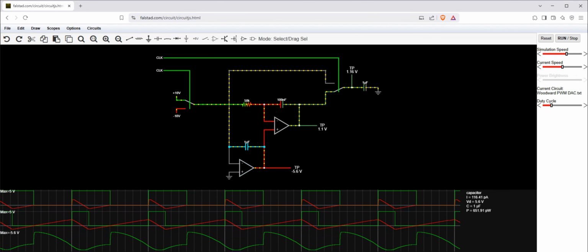The quadratic shape is the result of a mismatch in the on resistance of the normally open and normally closed throws of the analog switch, which can be estimated roughly by looking at the on resistance versus terminal voltage chart usually found in the datasheet. Getting Excel to fit a quadratic curve to the INL plot and subtracting it results in a residue INL of less than plus or minus 1 ppm, which is quite impressive for such a simple circuit.